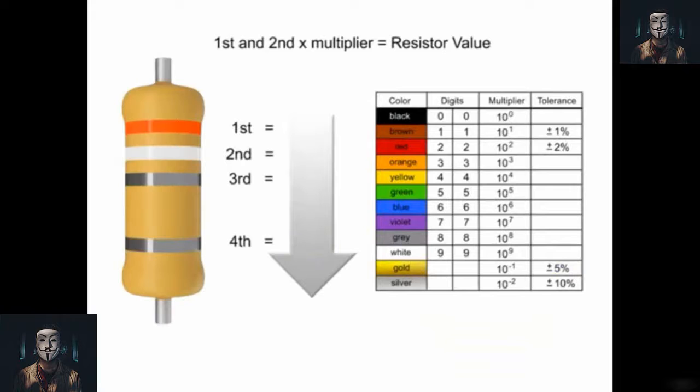A rheostat has one terminal connected to the fixed end of the resistor and the second terminal connected to a movable contact called a wiper. By changing the position of the wiper on the resistor, the amount of resistance can be increased or decreased. The most common use of the rheostat is the instrument panel light switch. As the switch knob is turned, the instrument lights dim or brighten depending on the resistance value.